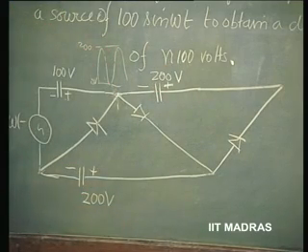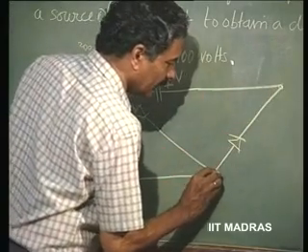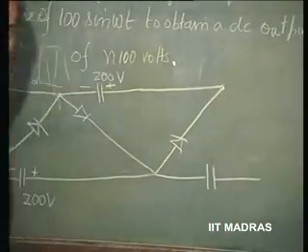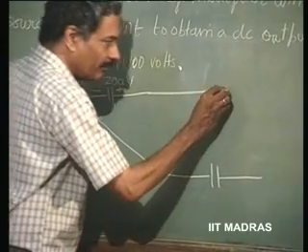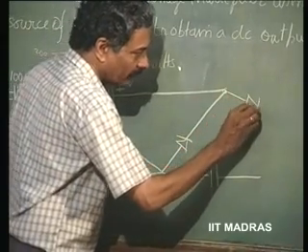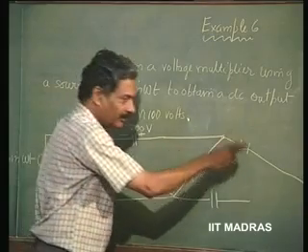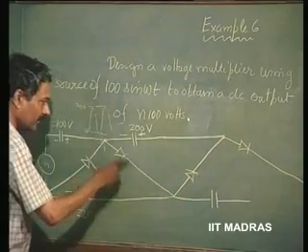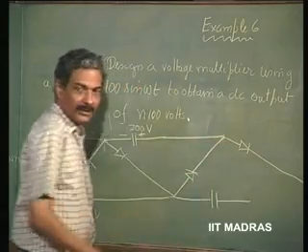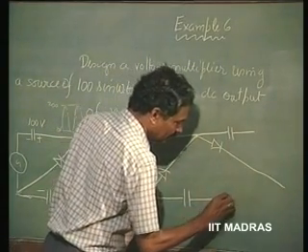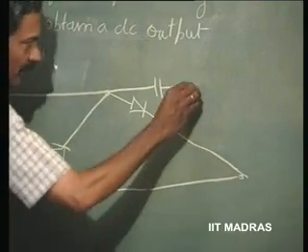So, this process can go on, and if you keep on doing this, and this is very easy to draw further, you can multiply it any number of times. You can see the pattern developing, diodes always going in the same direction, and the capacitors on either side of this kind of arrangement getting charged to respective voltages.